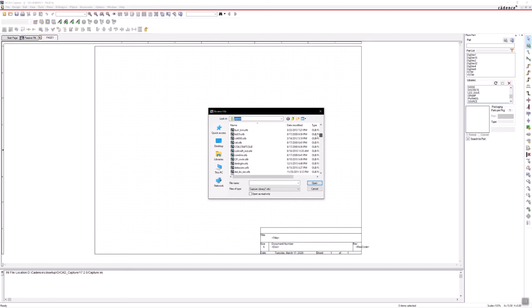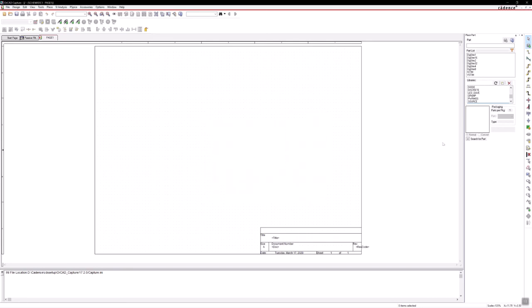That's where the analog one is, which of course contains our analog components, and the source library, which honestly for this simulation you only need analog and source as far as the libraries. So I'm going to go here to analog. I'm going to pull out a capacitor, and then I'm going to pull out a resistor.